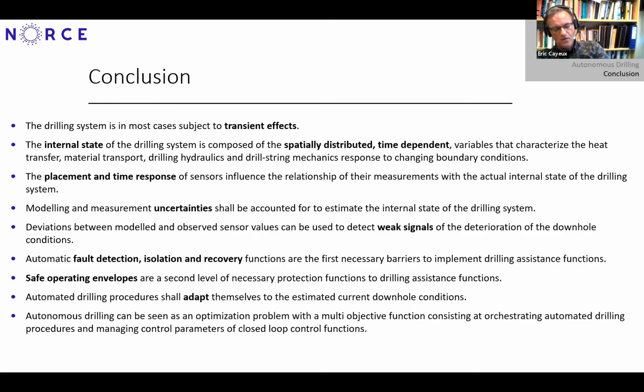All those models are running, the whole evaluation of the internal state is done at 100 Hertz, every 10 milliseconds, because things are happening very fast. And we are combining the effects of heat transfer, material transport, drilling hydraulics, and drilling mechanics.